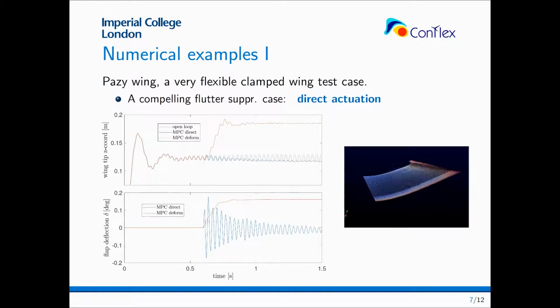And what we see is that when the MPC horizons that we use are shorter, the typical direct actuation mechanism is obtained here in blue, where the flap is deflected synchronously to the flutter oscillations. And this achieves a substantial reduction in the amplitude of these oscillations.